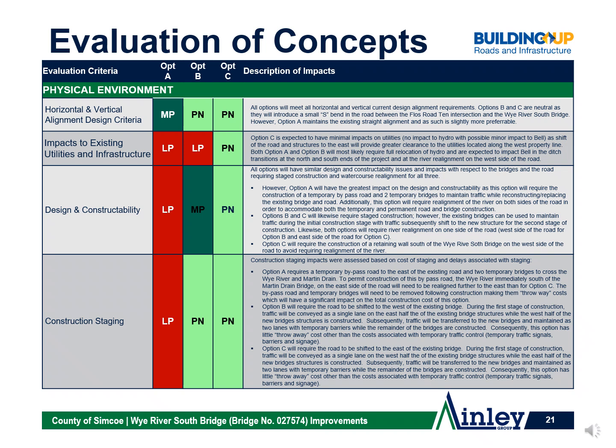Next, the options were assessed on their design and constructability. Option A was considered the least preferable given it requires the construction and design of a temporary bypass road and 2 temporary bridges, in addition to requiring 2 stream realignments. Options B and C will only require 1 stream realignment, and both will use the existing bridges to convey traffic, which will decrease throwaway costs from construction staging. However, option C will also require a lengthy retaining wall. This makes option B slightly more preferable than C.